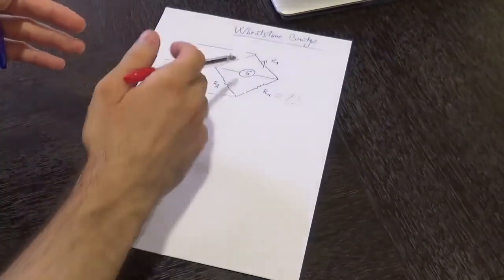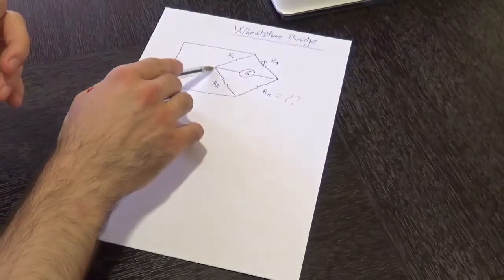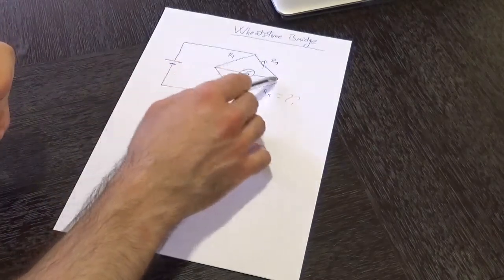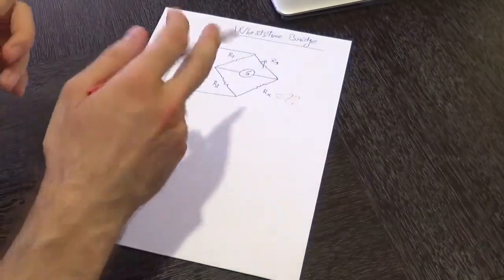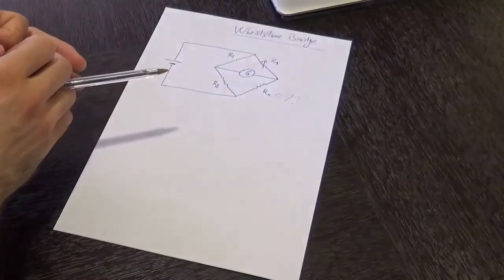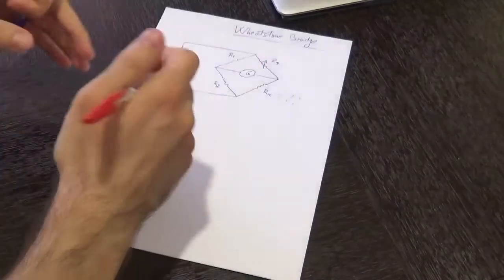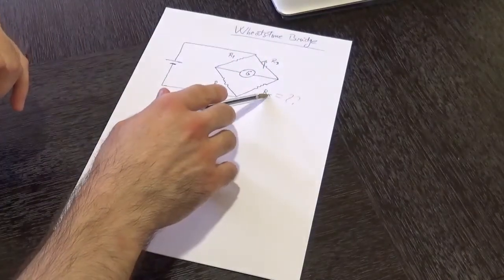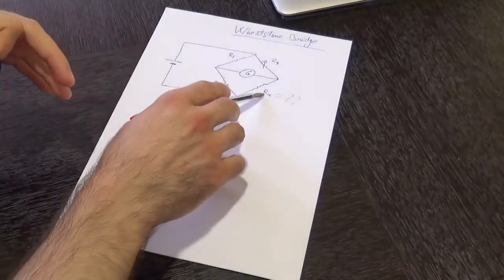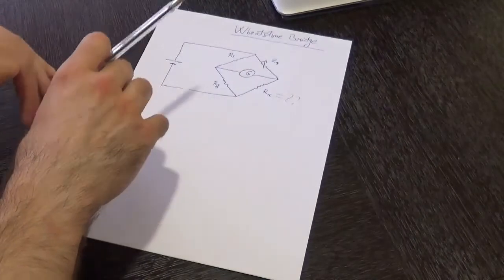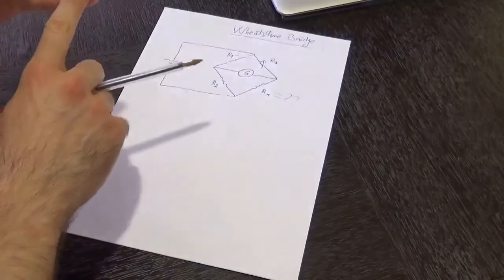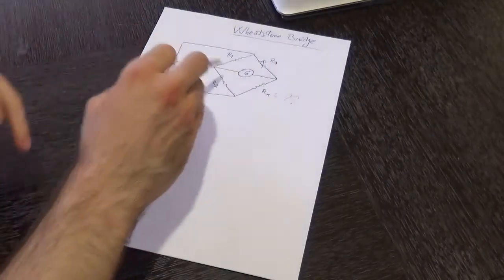So in order to balance out these two parts, the potential at that point should be equal to the potential at the opposite point. Therefore, the potential difference between these two parallel parts would be equal to zero, and in that case we have balanced out these two parts of that bridge circuit. So like I said before, the target over here is to find a value for that unknown resistor Rx. In order to find a value for that resistor Rx, we need first to establish an equation for that resistor Rx. So we are going to be applying KCL and KVL to our circuit over here.